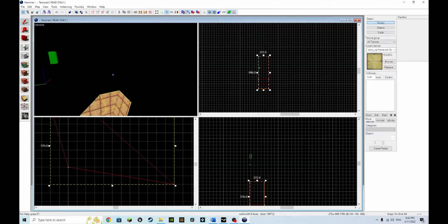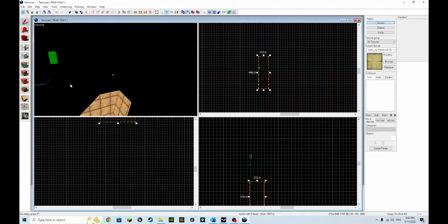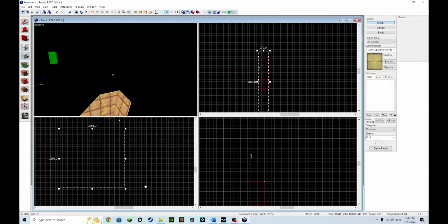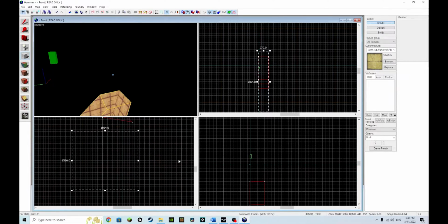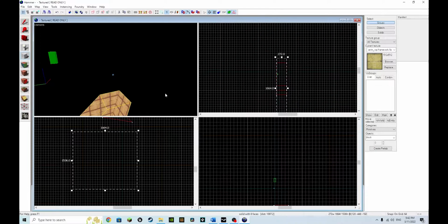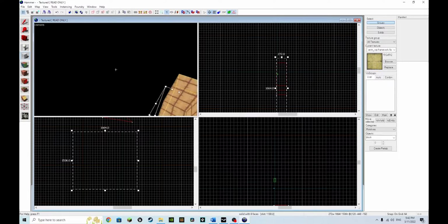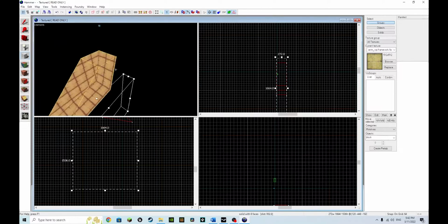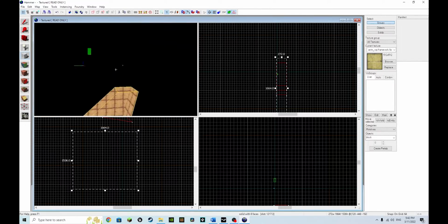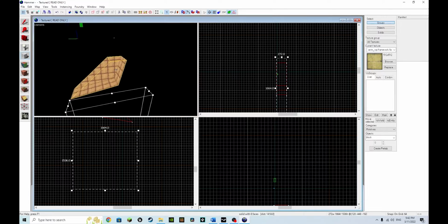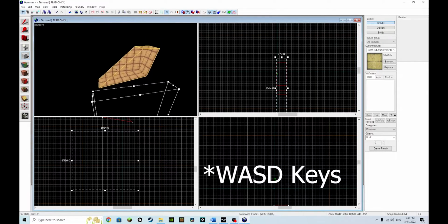Okay, now we're going to talk more directly about the brush/block tool. You can select it and drag a box onto one of the grids, which is pretty easy. Also, to move around the 2D and 3D viewports, you can hold space and use left click, not right though, to move around in these. Also hold space and click the mouse to the right to orient around a point, or just move like this. Left to move and look around, and you can also use the arrow keys to move around too.